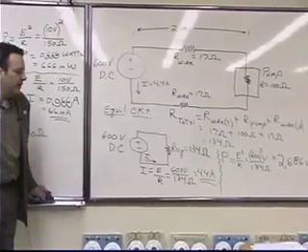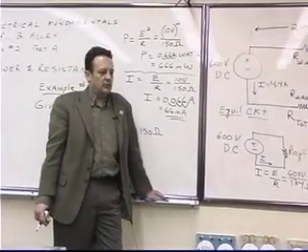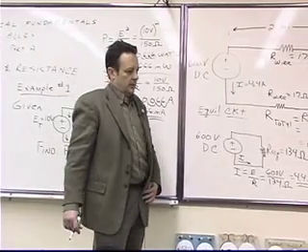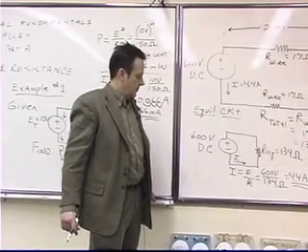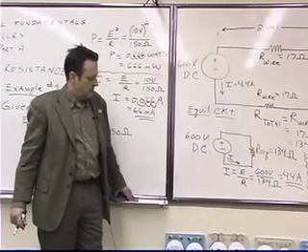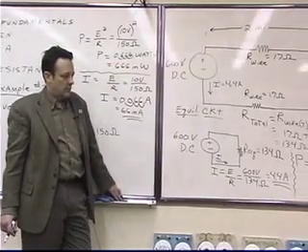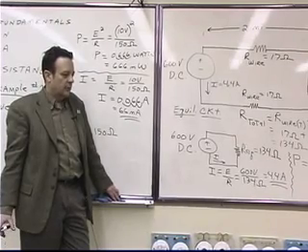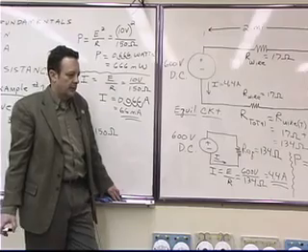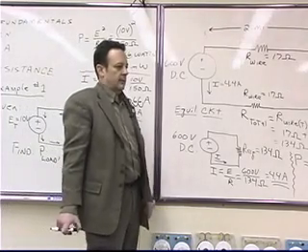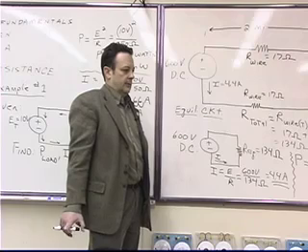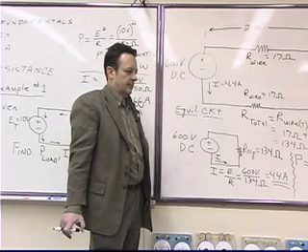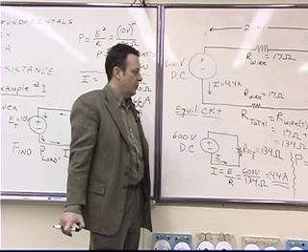Now, is that a valid method? Is that a formula in the Ohm's law wheel? Yeah, but you get a different answer if you multiply amps times volts. E times I equals VA. So we're talking about apparent power. E times I, that's what it says here on the wheel. But you get a different answer. It's off by about 40 watts.